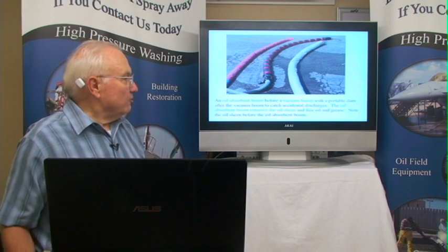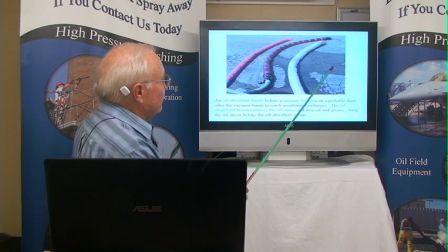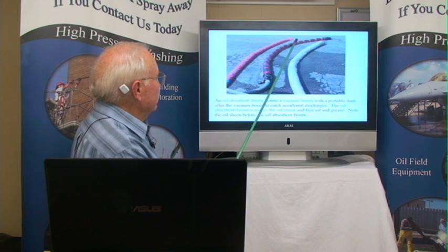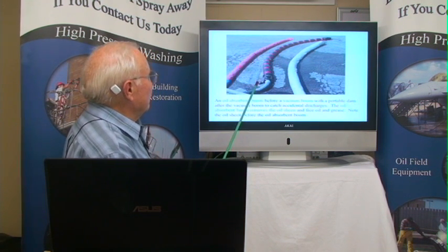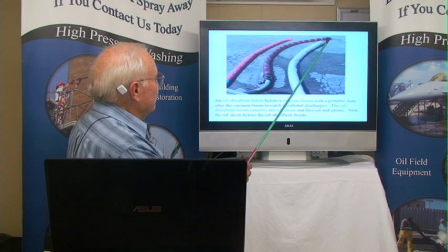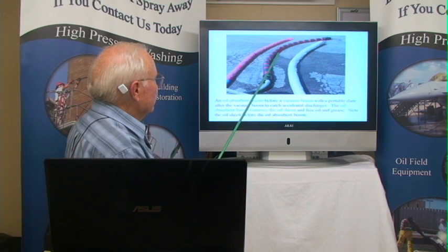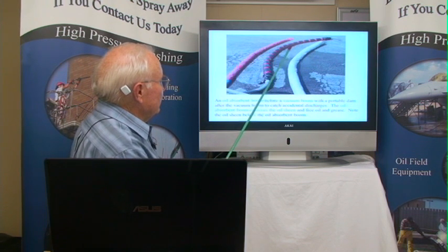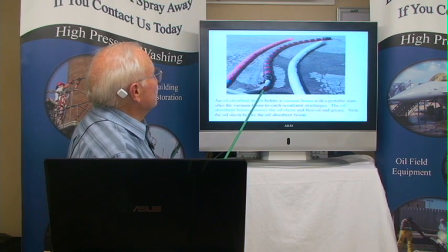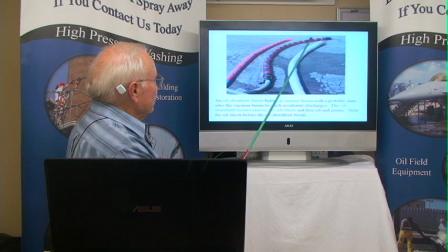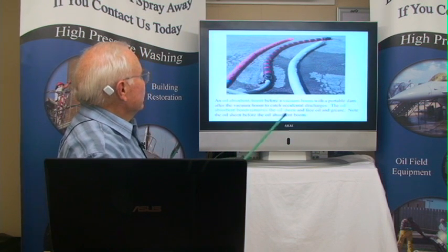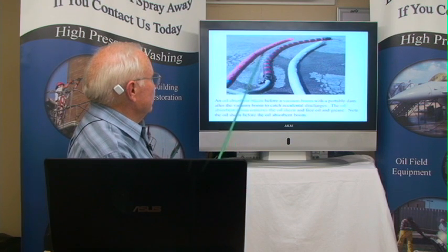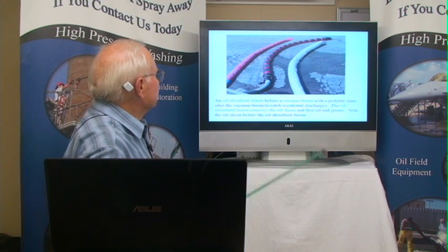There's a picture of the oil absorbent booms. I don't know if you can see it or not. There's oil sheen coming in right here. There's no oil sheen here. And by here, it's dry. This is a vacuum boom. It's got several ports here. And there's lots of sources, and there's vacuum berms. They're basically the same thing. And this is hooked up to a vacuum system to where it will pull all that. Get with your individual vendors for these particular products.